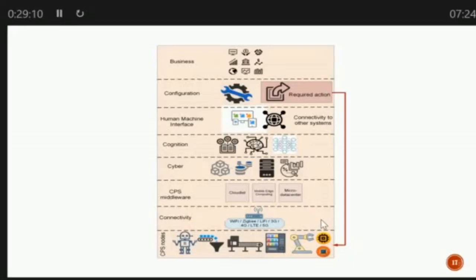Visible light communication would be really handy in case of industrial setting because most of the industrial devices would be static. So you have a visible light directly beamed at a particular device, and hence the bandwidth would be much better and there would be no interruption. So that's a huge future potential and use case of visible light communication or VLC in terms of industrial IoT. One of the examples of visible light communication is Li-Fi, L-I-F-I, this one.